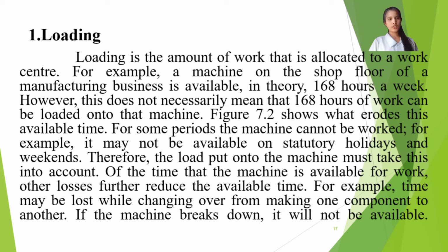Number 1, loading. Loading is the amount of work allocated to a work center. For example, a machine on the shop floor of a manufacturing business is available in theory for 168 hours a week. However, this does not necessarily mean that 168 hours can be loaded on the machine. For some periods the machine cannot be worked. For example, it may not be available on statutory holidays and weekends. Therefore, the load put on the machine must take this into account.